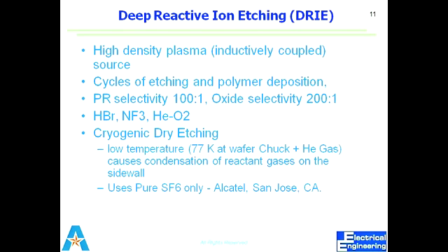Okay, so as I told you, deep reactive ion etching uses high density plasma. I talked about types of coupling last time: capacitive coupling and inductive coupling. I told you that inductive coupling is used to produce high density plasma, and capacitive coupling is not used to produce that high a density. It's usually low density, or even medium density is okay. So it's high density plasma. If somebody asks what is the mode of power you are generating here, it would be an inductively coupled power source.